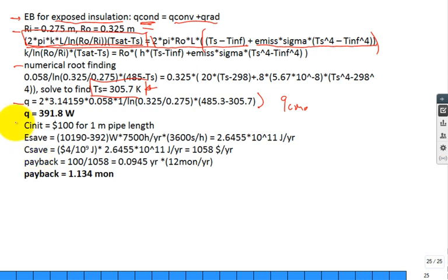And then this is also payback, so make sure that you can work that part of the problem too. So you find out it costs this much to install it, and yet I'm going to have this rate of energy savings. Then how many months or years will it take for me to recoup my investment due to the savings on the energy that would have been lost because of excessive cooling of my pipe.